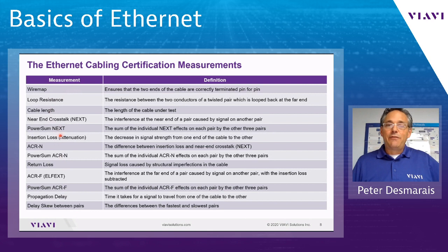These are the different standards for a TIA certification test. Again, there's 13 of them listed here. There's a couple other optional tests that you can do, but to certify a cable, these are the 13. The most common source of a failure would be near-end crosstalk. And that kind of plays into a lot of the others. So if it does fail near-end crosstalk, it's going to fail power sum near-end crosstalk or attenuation to crosstalk ratios and stuff like that.